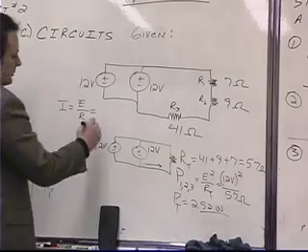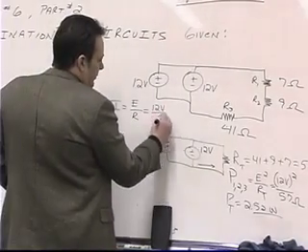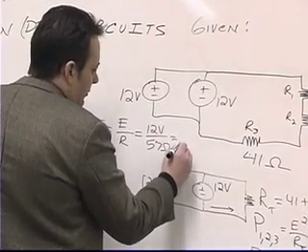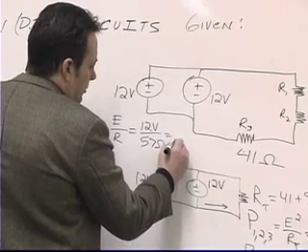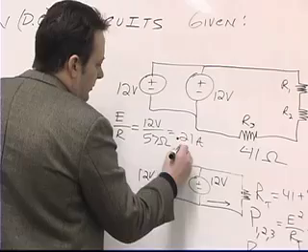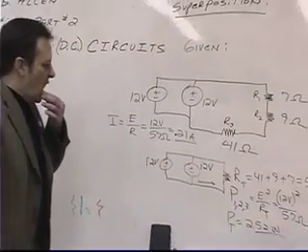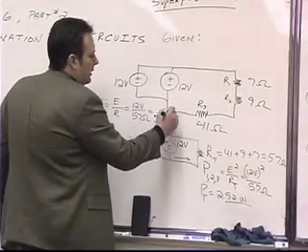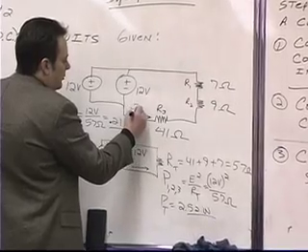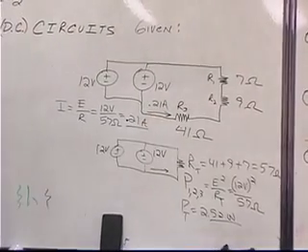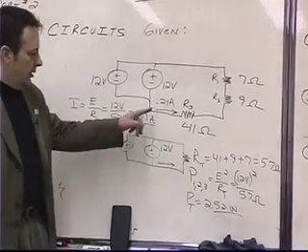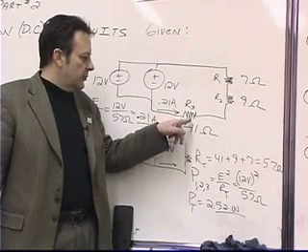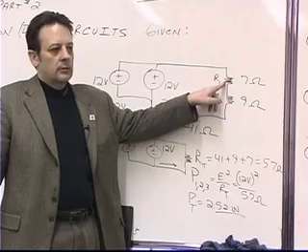0.21 amps. Right, so that would be 12 volts divided by 57 ohms, which is equal to 0.21 amps. Okay. Now, since these are equivalent circuits, would it be fair to say that the current here would be 0.21 amps? Okay. So if the current here is 0.21 amps, do I have enough information to calculate the power distribution here, here, and here? Yes. Okay.